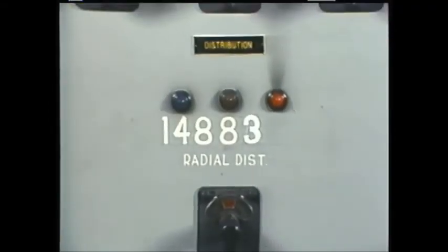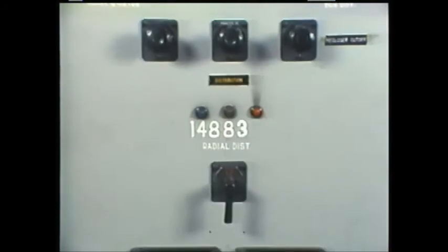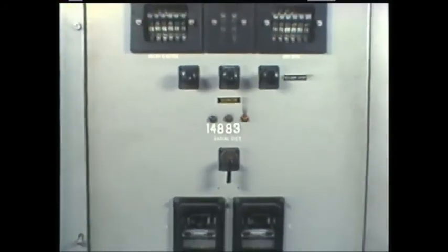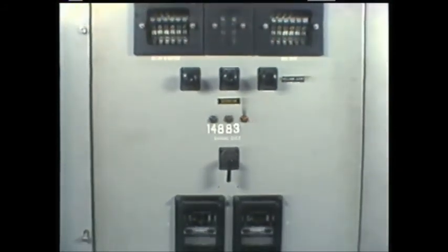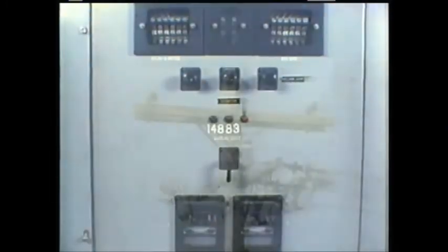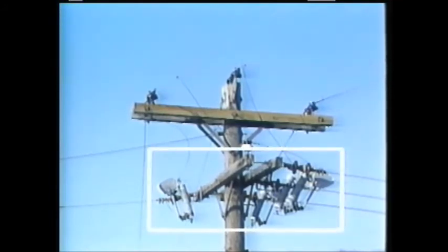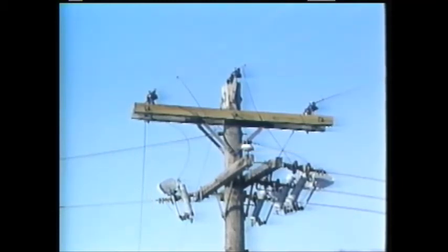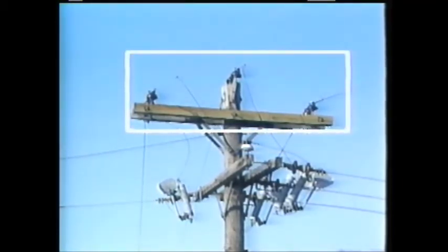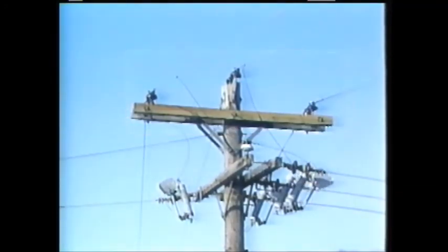Circuit breakers provide excellent protection against damage due to faults on feeders. Circuit breakers can also protect laterals that are tapped off of feeders. However, in many systems, fuses are installed between the feeder and the laterals to provide additional protection. In this example, the feeder supplies a 3-phase lateral and a single-phase lateral.